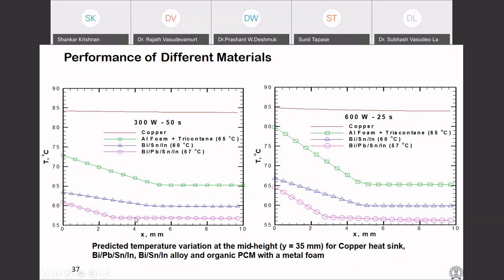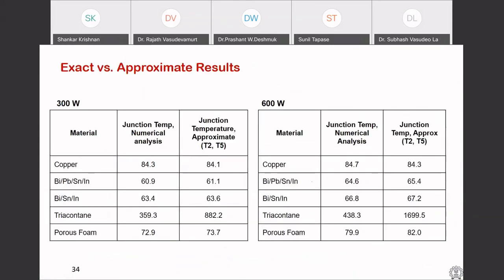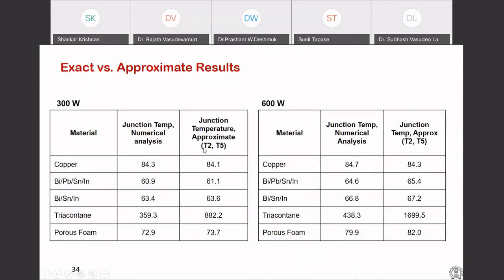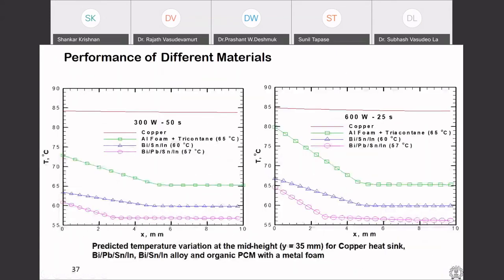So you can successfully reduce the thickness now. You can even add a factor of safety and make it 4 mm, because the lead alloy has almost the same density as copper, as you can see from the properties here. So you are able to cut down the thickness significantly. About 6 mm, at least 2 mm can be reduced.